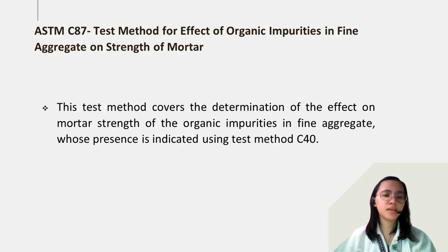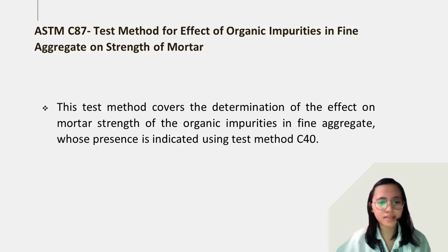So, this is what I was saying earlier, that our previous test, C40, resulted in a color darker than the standard color. It is advisable to perform the test for the effect of organic impurities on the strength of mortar, which is this method.